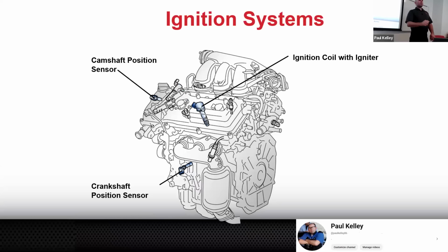If you start it and it's still misfiring and now it's a P301, what do you think the failure is? Do you remember we moved the coil from 3 to 1? Exactly. But what if it was a P305? Exactly. And you're like, and that took you how long? Not much time. So that's legitimate diagnosis. It's not that cool. You don't have to be that smart. But if you keep it simple, stupid, that's what I would do.